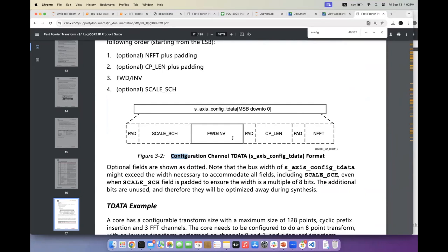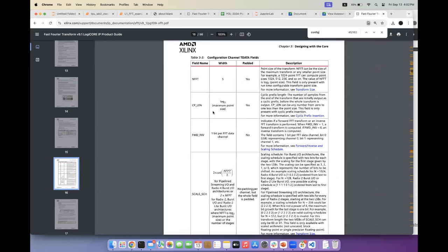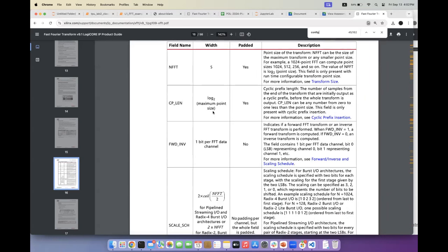And you must know that our hardware is using a custom fixed point format. Does anybody know what a fixed point format is? You can search it and believe me, it's not hard. So basically, in a fixed point format to store complex numbers, you have a 32-bit number, you divide it into 2 16-bit numbers, and you multiply by the scale factor, and you can convert it into complex numbers. You should do that in your homework. Okay? Does it make sense? Am I clear?